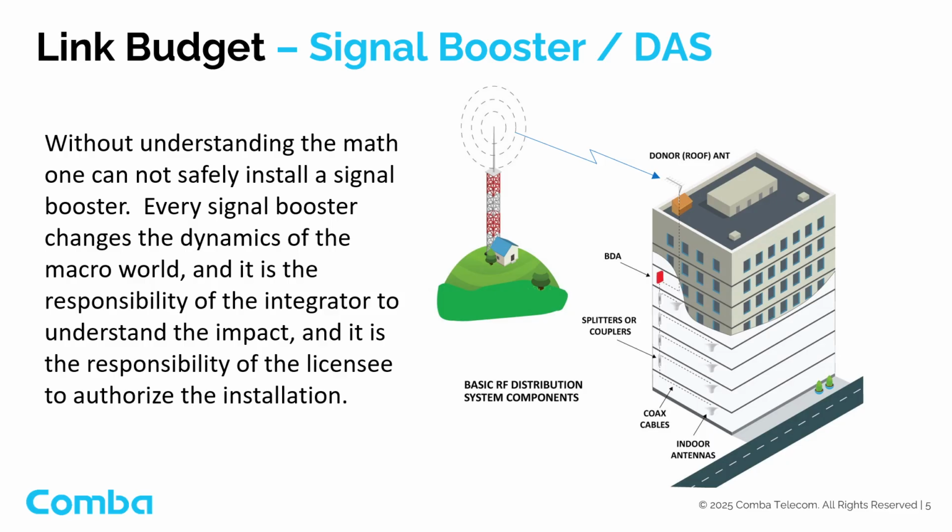During commissioning, only minor adjustments should need to be made to optimize the BDA performance and provide sufficient coverage levels. If the initial RF link budget estimated levels are close to the actual field measurements, the BDA operator can be confident the system is working properly. If the actual field measurements differ greatly from the initial RF link budget, the BDA installer and operator can perform further troubleshooting to determine if there are issues with the installation or components in the system.